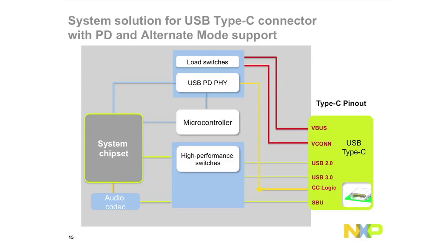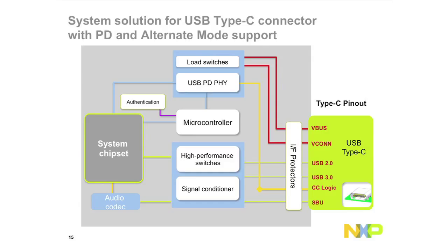And then finally, you'll need some signal conditioner on the path. So again, depending on your signal integrity budget, the losses through the entire system, you'll need some sort of redriver in the path. And of course, some filtering and ESD protection for your port itself, for the physical connector that we all are very familiar with. And finally, I'll touch towards the end.